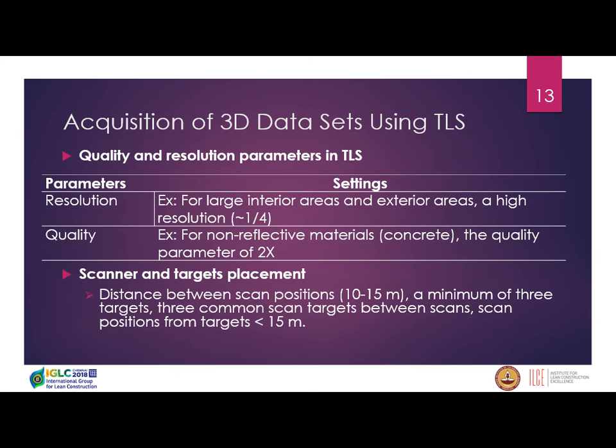We need a balance between the time needed for data acquisition and the level of quality and resolution. And it's better to have a higher number of scans at lower setting rather than a lower number of scans at higher setting.